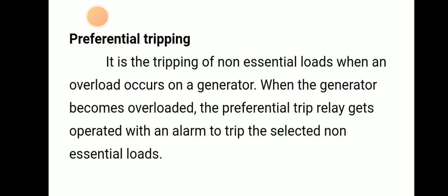Today we will be discussing preferential trip. Why is preferential trip used on board? Preferential tripping is the tripping of non-essential loads when an overload occurs on a generator. When the generator becomes overloaded, the preferential trip relay gets operated with an alarm to trip selected non-essential loads.